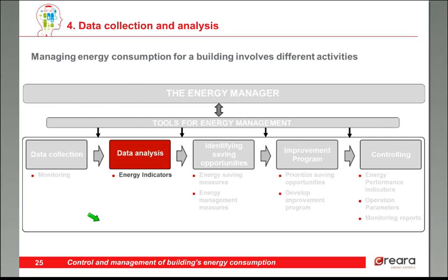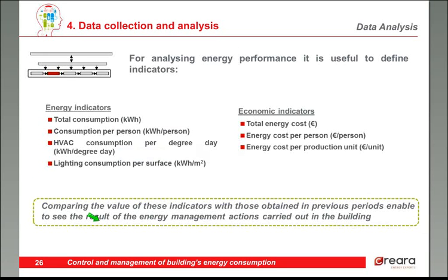Data analysis. Once the consumption data has been collected and different energy users identified, data analysis is needed to understand the evolution of the energy performance of the building. And for this, indicators are needed. I would say that essentially two different indicators are useful. One is energy indicators, and the second one economic indicators. And taking into account these two dimensions is what generates the most complete and insightful analysis.